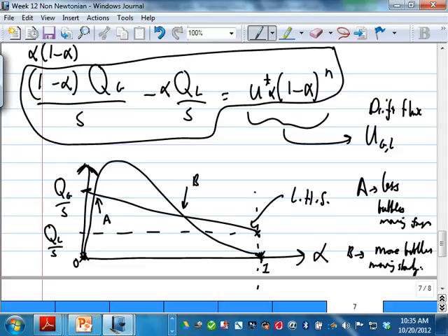So I told you when there are more bubbles, they tend to cause a traffic jam, they tend to slow down. When there are less bubbles, they tend to move faster. To give you the same mass flow rate of gas, you could have either less bubbles moving faster or more bubbles moving slower. So this particular system can actually have two solutions. And both solutions will satisfy the gas flow rate and the liquid flow rate.